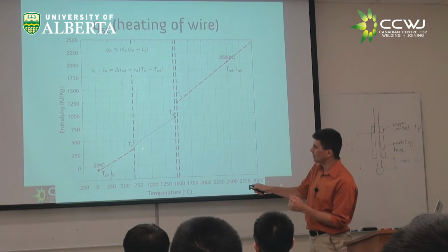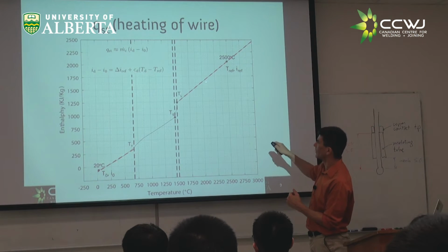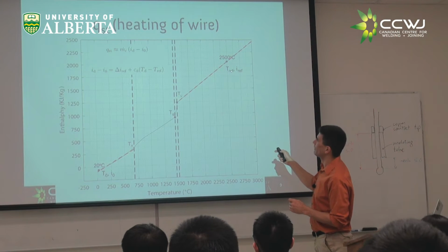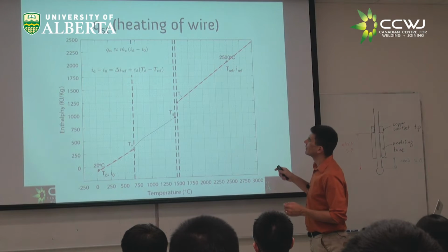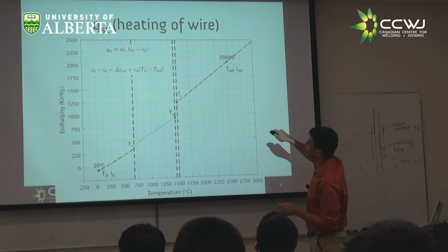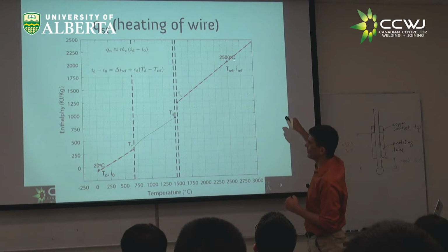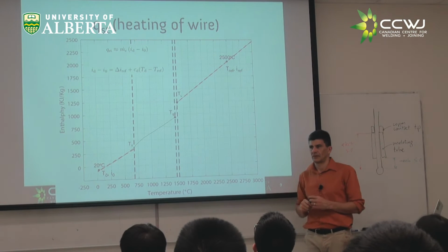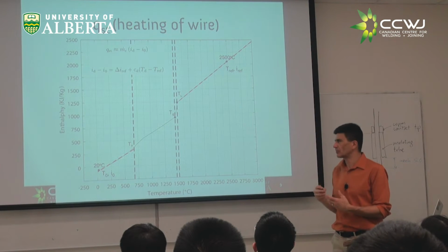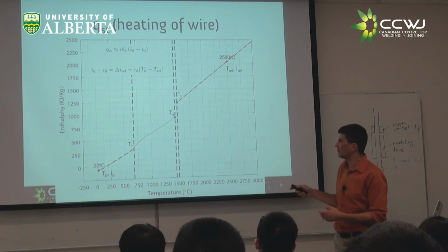And that accounts for the transformation from ferrite to austenite, accounts for the latent heat of melting, accounts for the specific heat, right? That accounts for everything from 20 to 2500. And then I'm going to say, well, the droplet might be a little bit hotter, might be a little bit colder. So I'm going to account for the specific heat of the droplet as it varies here. When we do the formulas, you're going to be doing them yourself, so you'll get the process memory of this.